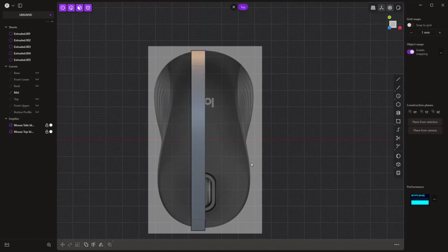Now, this is where it gets tricky not having a 3D model because part of it disappears here. The other thing that makes this tricky is we have to be mindful of tangency at the midplane. And the reason for that is because when we mirror this across, we need to make sure there's not a seam there. So the way that I like to do this is I like to generally build part of the surface or part of the curve here.